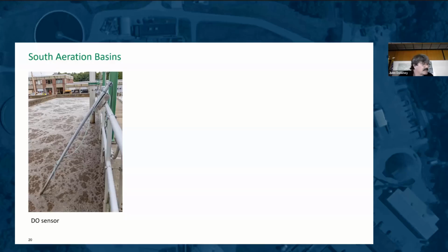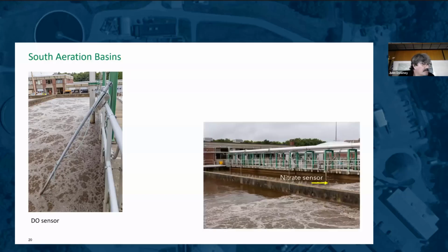Here are some of the south sensors. On the left is Basin 7 ammonium sensor. We recently had to move this to accommodate the efficiency of the conversion in the aerated zone that had been downstream. And we found we were converting ammonia faster, so we weren't maintaining 1 part per million for enough of the day for that to be a viable spot. So we brought it back upstream here. The center photo features the Basin 6 upstream NO3 sensor located at the end of a very long anoxic section. It gives you a better idea of how we're treating the recirculated liquid.